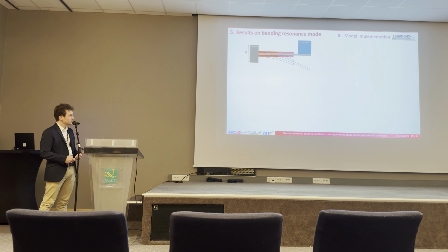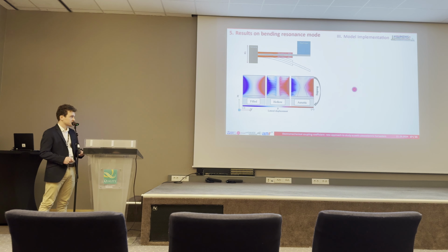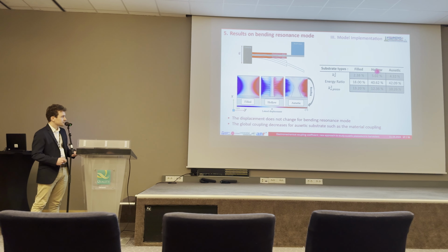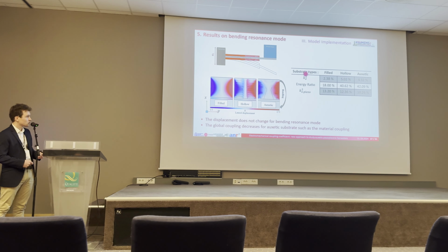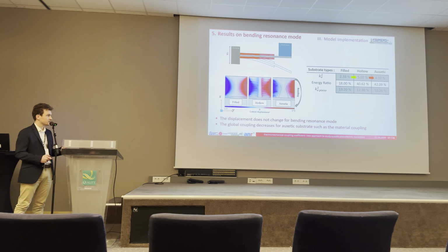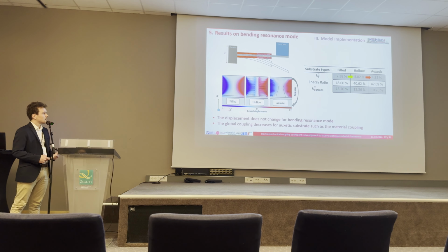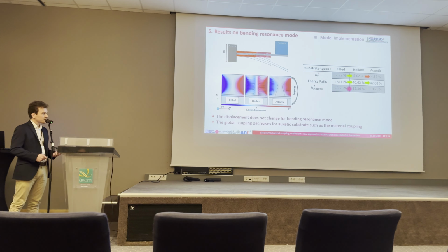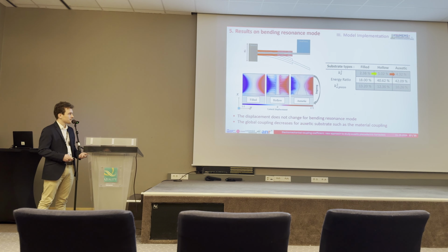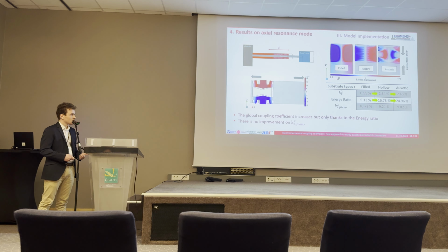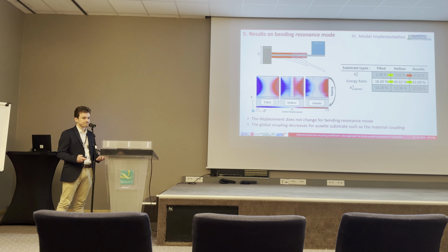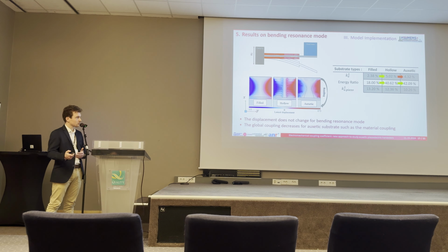Then on the bending resonance mode here, we don't see any auxetic behavior anymore. And at the same time, on the results here, we see the global coupling did increase for the hollowed one, but decreased for the auxetic one. The energy ratio did increase between the filled and the hollowed, but not so much with the auxetic one, inversely to the previous one here. And the material coupling here decreased with the hollowed and auxetic substrates.